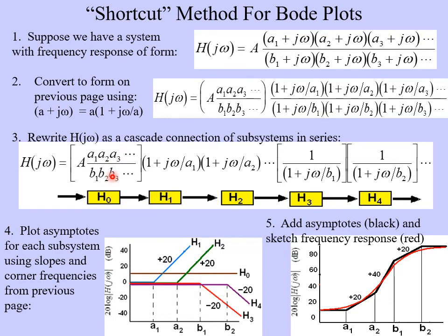And so we have to convert it to decibels. Well, that's easy. We just take the log of this number and multiply it by 20. So that's going to be H naught. All right, that's this line here. So in my example, let's say it turned out to be 10 decibels. So I would plot that right here. Okay, and notice it's labeled H naught.